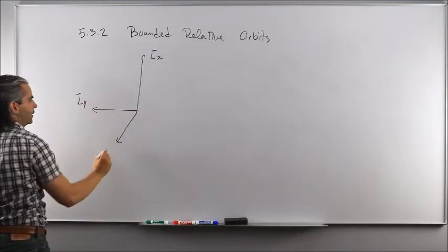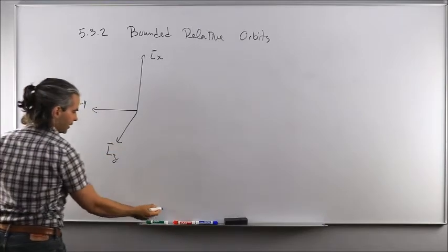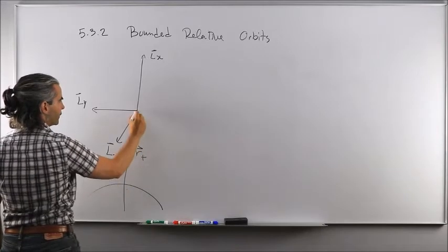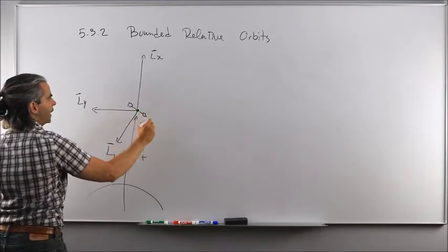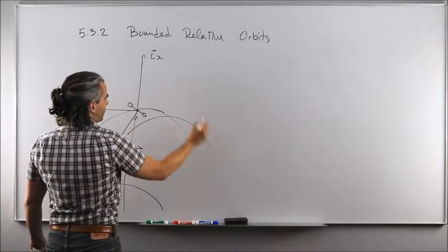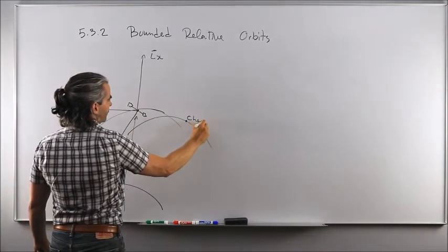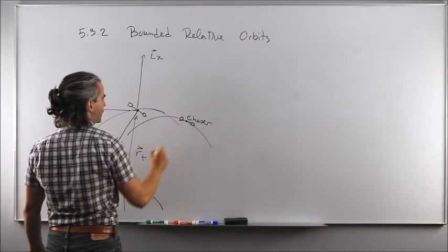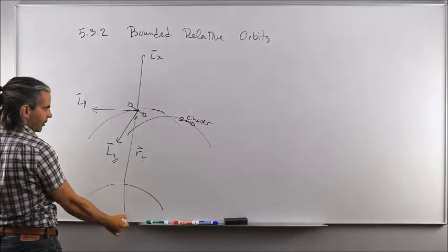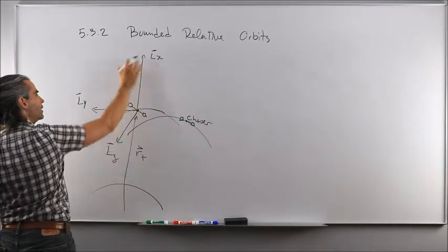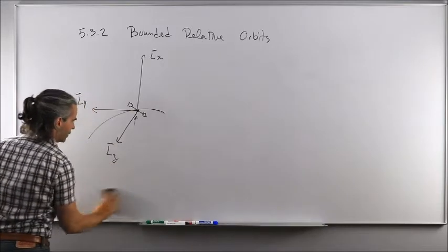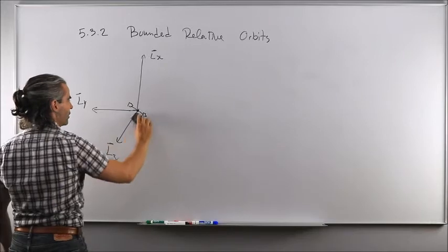Lx, Ly, Lz pointing at you. Okay, so this assumes that the Earth is somewhere here. RT position vector looks like that. So we have the target spacecraft here, riding along its orbit like this, and you have another orbit where the chaser spacecraft exists. Okay, so both spacecraft evolve along their respective orbit, seen from the ECI reference frame centered at the Earth here. But if you were to look at just the relative motion seen from the target's point of view, all right, so we forget about the Earth because that's not what is interesting here, but rather the relative motion,